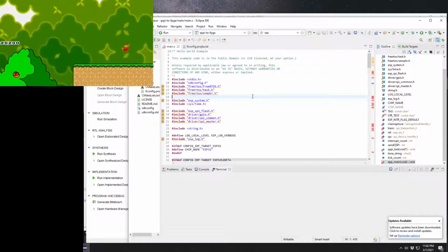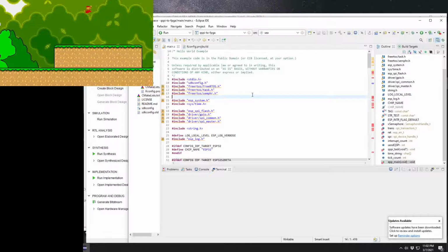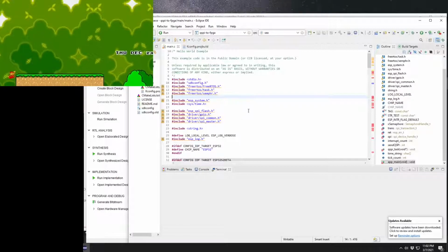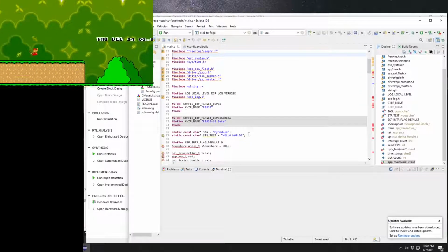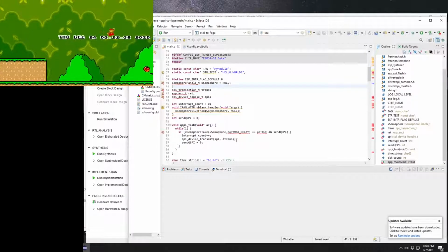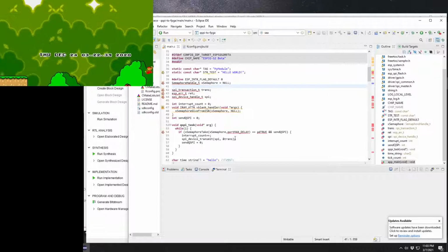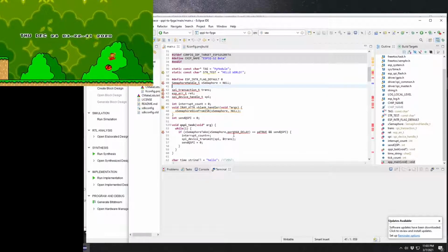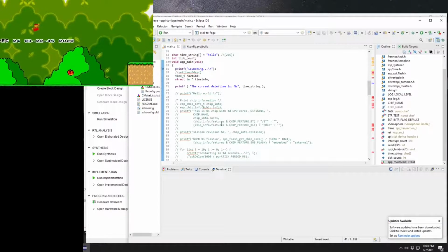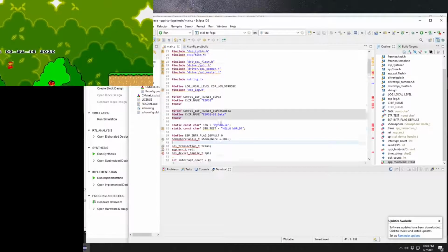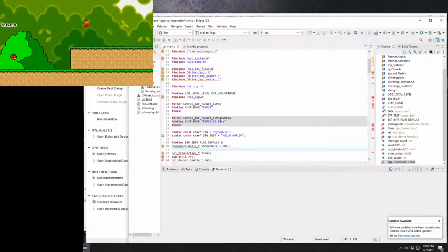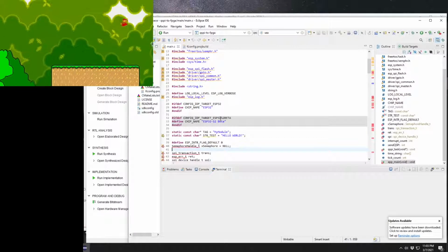And fortunately, after a lot of searching and scraping of GitHub and forums and whatever documentation I could get my hands on, I did find instructions on how to set up the QSPI using the ESP IDF for kind of arbitrary transactions. So I get to have a lot of control over what data is sent and when. So the short version of how we do this, we send QSPI transactions, right? So we send 4 bits per clock cycle using dedicated hardware in the ESP32.